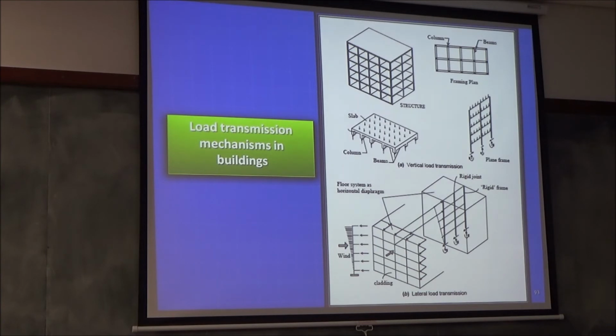In practice, people say, look, wind is acting on this wall, and this tributary area is 2 times this tributary area, so 2 times the load will come here. That's not how you should do it. You should get the total load on the building and distribute it to the frames in proportion to their lateral stiffnesses. And the end frame will have a larger stiffness.